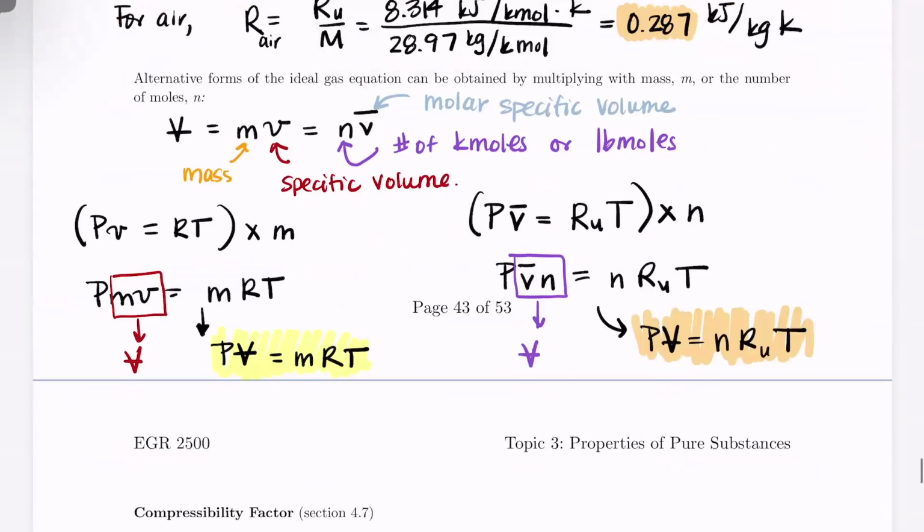Oh, sorry, before I go on, a couple of other key notes that I already mentioned, but I want to draw your attention to them. Temperature must be absolute, so it needs to be Kelvin or degrees R. Sometimes for certain problems we can use either Celsius or Kelvin, or Fahrenheit and Rankine, but that's only if we're doing delta T, where differences in those units are equivalent.